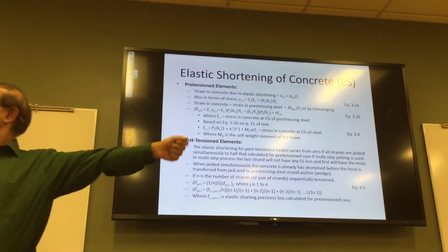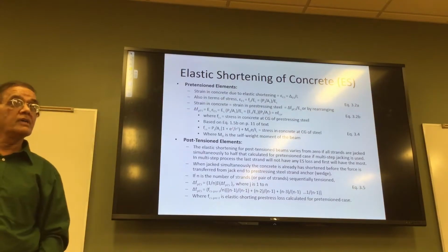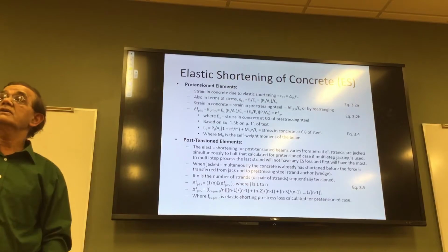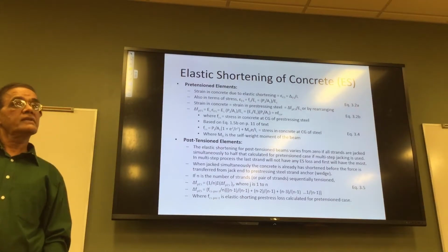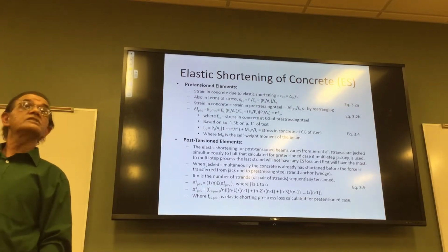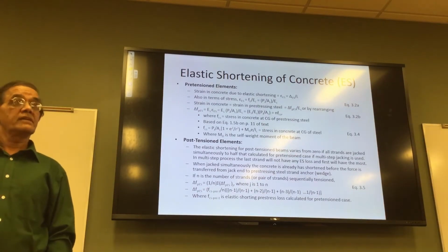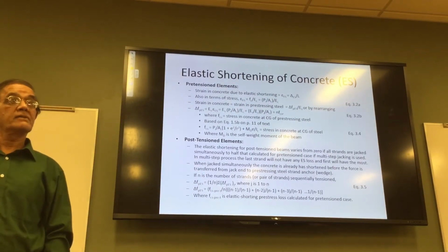So if you have a wire stretched between these 2 walls, and I move this wall 6 inches, the tension you had in the wire is now accordingly lost. And how would you calculate that? You say 6 inches divided by the length of this room. That is your strain. Then you can calculate this is the loss of strain, right?